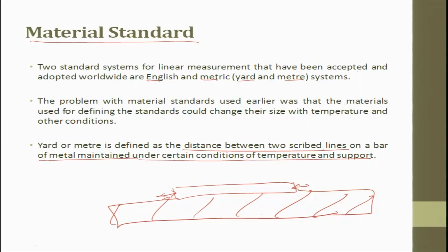Same way, when this is in perfect contact with the table, it can expand or contract. When the table expands or contracts, and if the scale which is touching it is having a surface contact, then this influences both. So, in order to avoid this, what people do is they take a table, have pointed supported loads, and then they have a scale, and we try to maintain the temperature and other conditions for the entire setup.